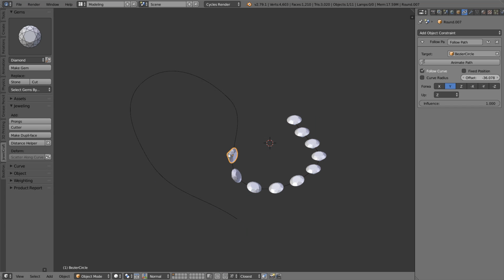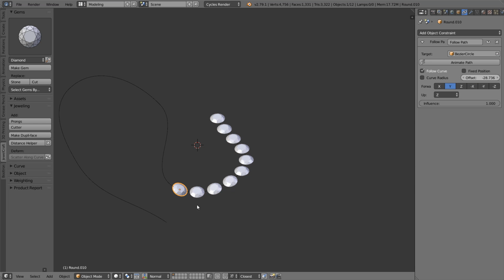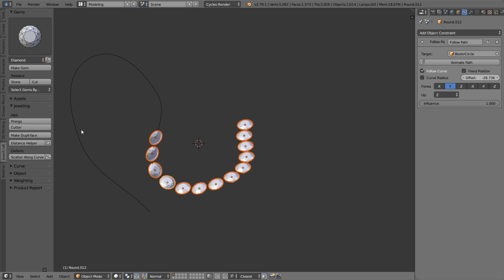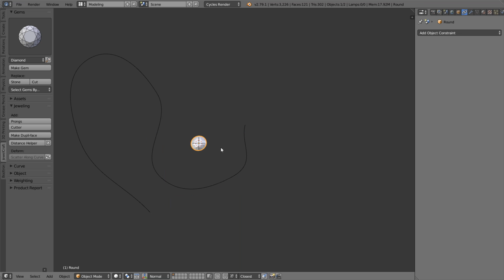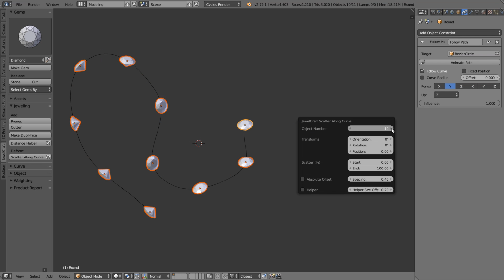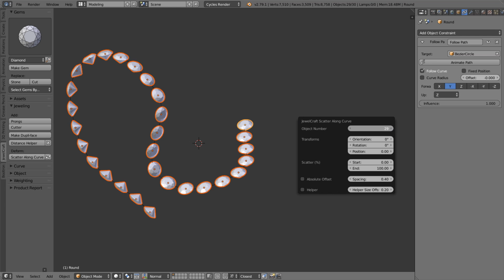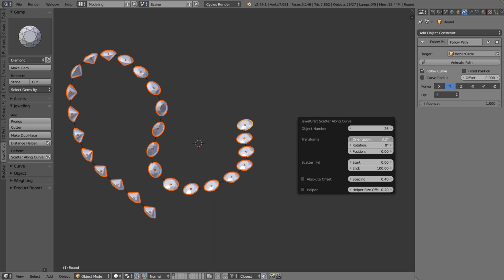Here is a quick hack for you on how to increase the number of stones using Redistribute. Use the Duplicate tool. Copy the stones and press Escape, intentionally creating duplicates. Then select all the stones and use Redistribute. Or you can remove all the stones but one and redistribute them with the Scatter tool. But before this, do not forget to remove the constraint from the remaining stone. Functionality for scattering stones of different sizes has not been implemented yet, but it will be in future releases.